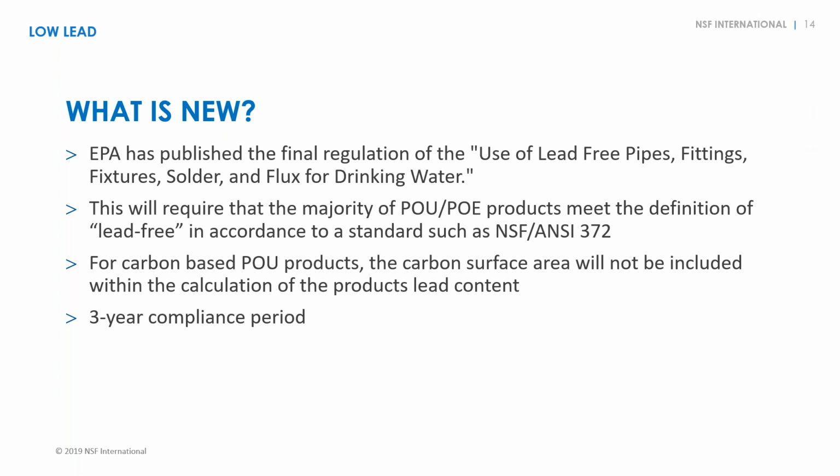And within the new regulation, they will now essentially require that the majority of point of use and point of entry products meet the definition of lead-free in accordance to a standard such as NSF/ANSI 372. And NSF 372 is the low lead standard, not to be confused with a lead reduction claim under standard 53, but it applies to all product types in contact with drinking water.